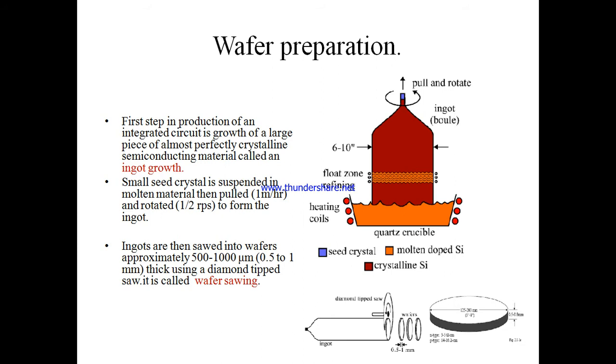Wafers are cut from ingots of single crystal silicon that have been pulled from a crucible melt of pure molten polycrystalline silicon. This is known as the Czochralski method. Controlled amounts of impurities are added to the melt to provide the crystal with required properties. The crystal orientation is determined by a seed crystal that is dipped into the melt to initiate single crystal growth.